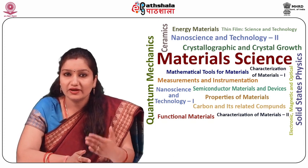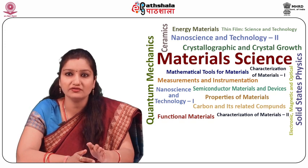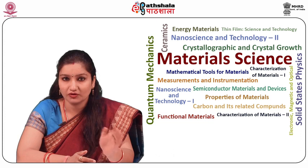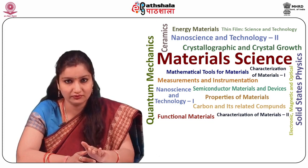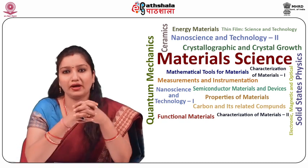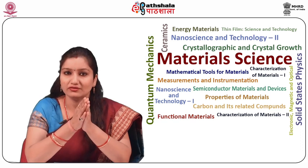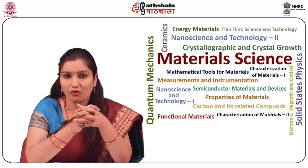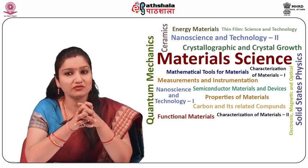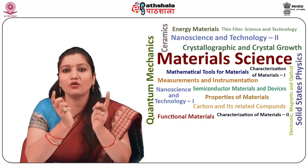Secondly, failure starts on the surface or near the surface, locally in places of stress or strain concentration. Local stress concentrators are formed by surface defects appearing on cyclic loading or notches as traces of surface treatment or the effect of the surrounding medium.